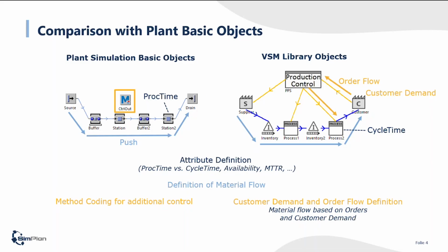This can be an information flow push or even a supermarket pull in different instances, but that might be an additional focus of that lean management area, where you have a more aggregated view on a shop floor with standardized icons for supplier, customer, processes, and inventories. Based on that, you would have material flow and also an order flow to trigger material flow in the stations themselves.